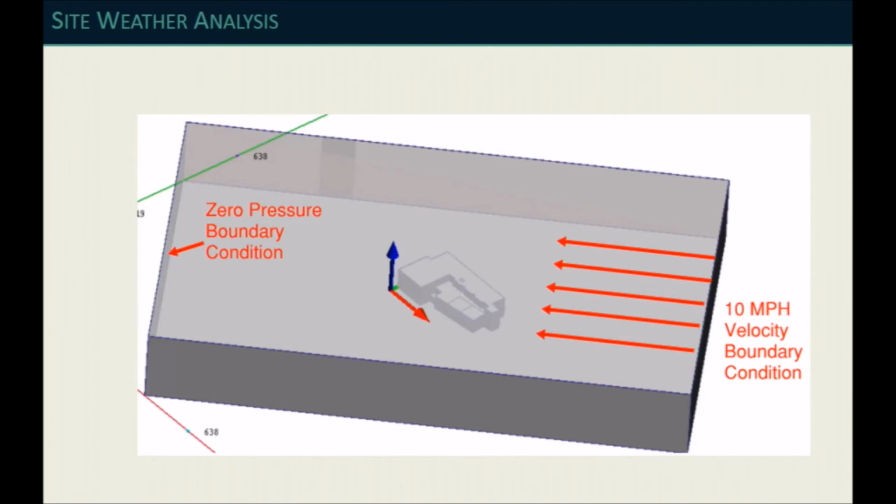Okay, so because we have a backup radiant cooling and heating system, I was primarily concerned with the average conditions. So you might also consider using something lower. We could use a standard deviation lower than average to sort of represent the worst case scenario, even though zero wind would be the worst case scenario.